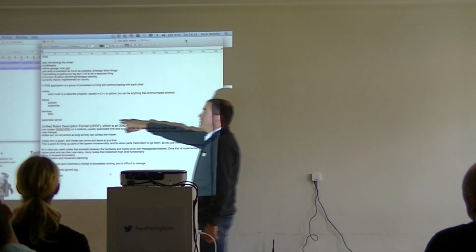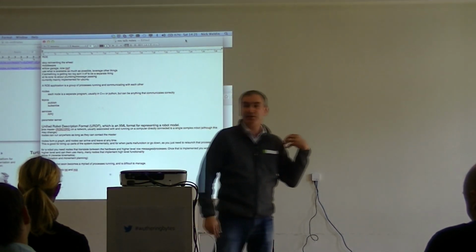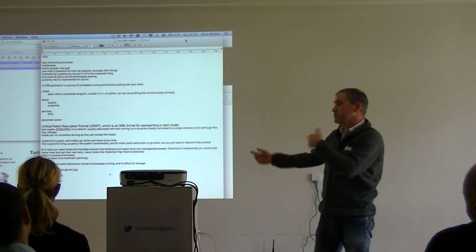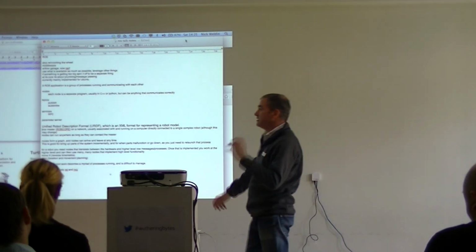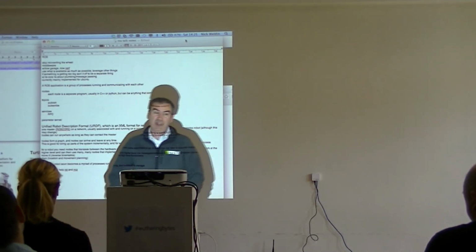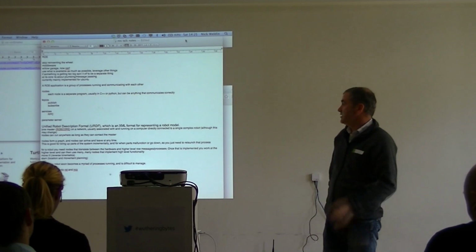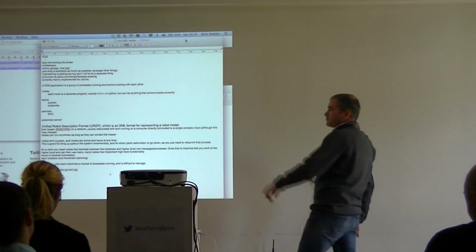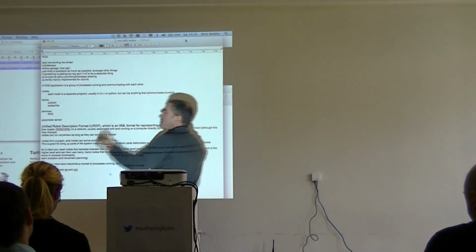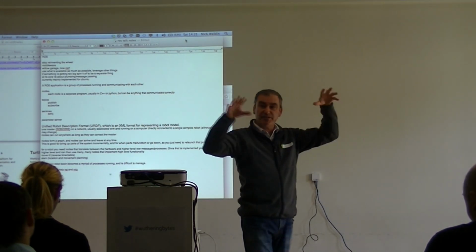Or they can provide services, which is basically that you can ask for something and it will send you something back. So topics are about broadcasting and receiving, services are asking and getting something back. And then there's a thing called a parameter server that basically holds global variables, so you can ask it what's the current value for this, what's the current value for that. And the nodes can be launched independently and taken down so you can build stuff up slowly.